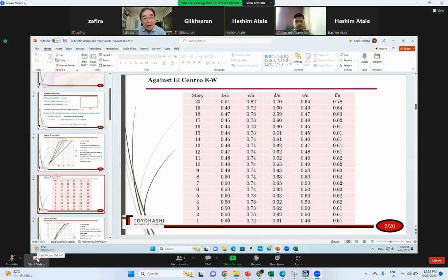Single TMD is good, and when the mass distribution is done based on effective mass ratio, it is the same as single TMD. The product of effective mass ratio and participation factor is the second good result. Equal mass is maybe the worst.